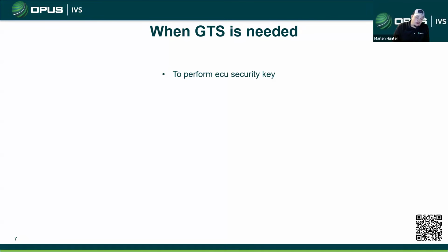So Toyota is kind of getting away from the used market, which is not new for a lot of manufacturers, but for Toyota, like I said, we've been spoiled for years to go grab an ECM out of another car, stick it in yours, jump 2 pins in the DLC for 30 minutes and fire the car up. So those days in the newer cars are kind of going away.